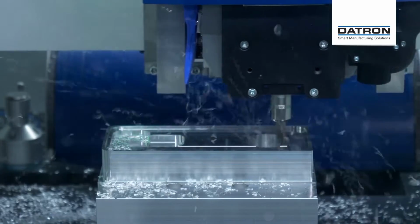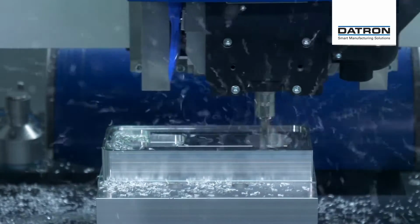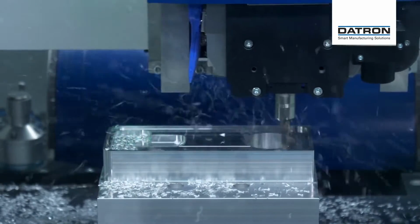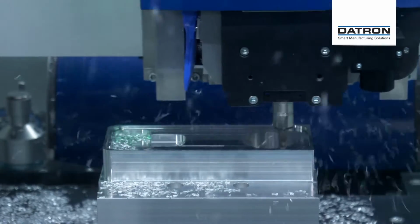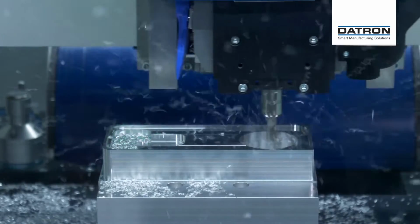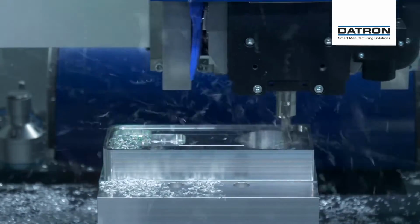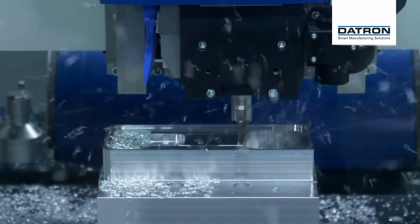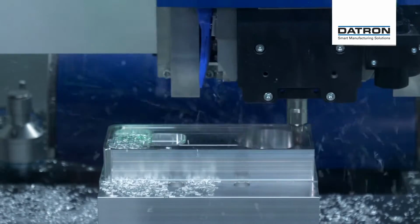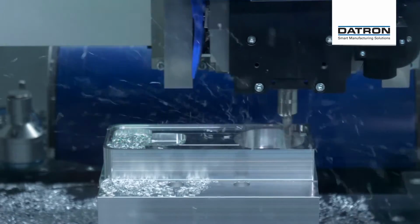If I have an overnight job running and I know that my tool will probably be wearing out after a certain number of hours or a certain path, we're able to put this tool a couple of times into the machine. So let's say we have this cross cutter 5 times in our machine. It's basically the same tool type, but it will automatically change from tool number 1 to tool number 2 once it's worn out.